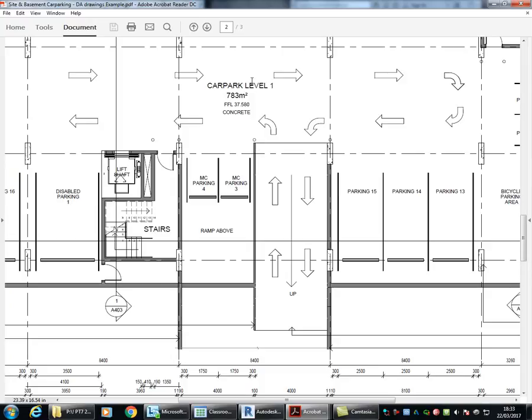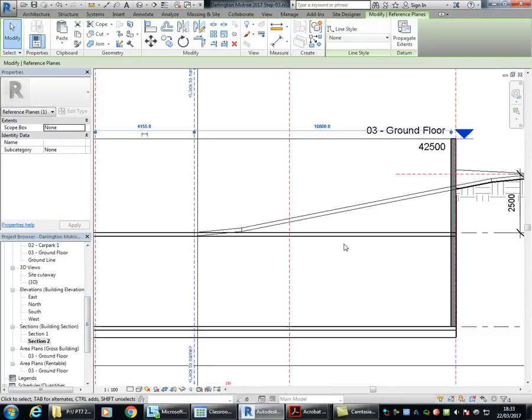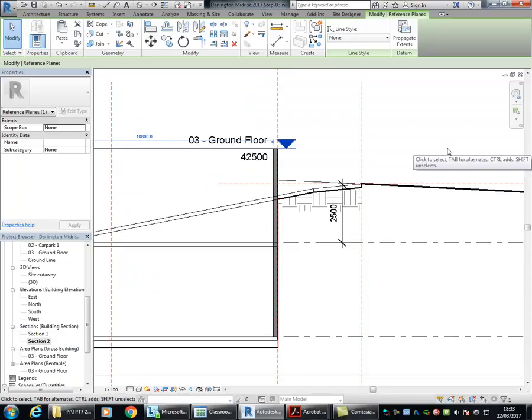So what's going to happen then if you move that? So you're basically moving the whole ramp so that it goes further outside the building, but then what's going to change? Exactly, that's right, because the ground's sloping outside. So if you move the ramp, then looking at the section again, it's accessing the ground at a lower point, so the slope will be less. Also, not the slope will be less, but the height will be less. And that means that it will be shorter, right? So that's going to then feed back into your other end.